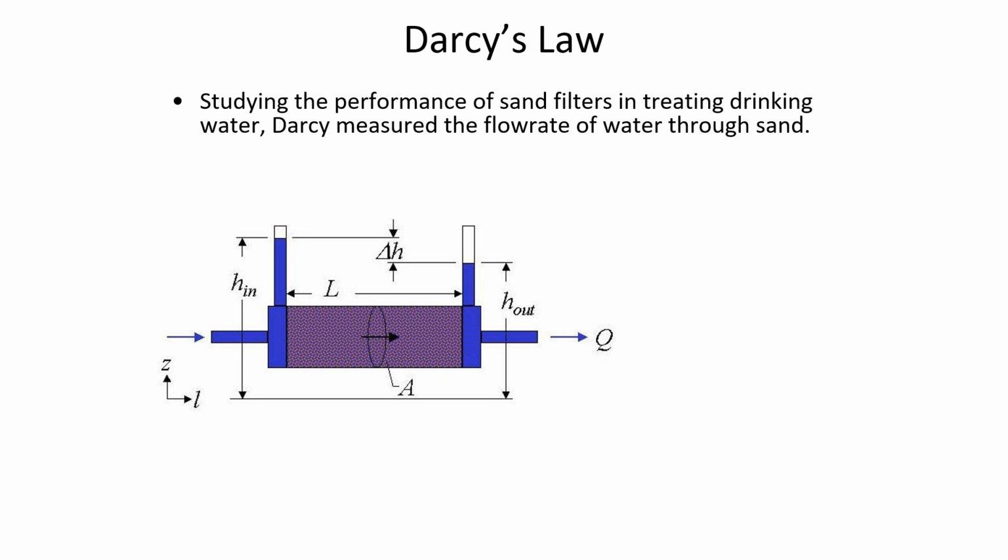And so that's the definition of a piezometer. The piezometer is measuring the effect of energy losses, not necessarily just reflecting the hydrostatic effect. So here, when it's on its side, we know that the pressure difference from one location to the other is negligible if it's horizontally oriented.